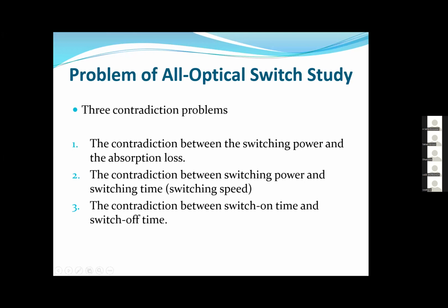The third one is the contradiction between the switch on time and the switch off time. In general, the switch on time of an all optical switch depends on the pulse width of the pump light. If the pump light uses picosecond or femtosecond pulses, the switch on time can reach picoseconds. However, because of the limitation in the carrier recombination time or the molecular moving speed, the switch off time is often longer than the switch on time, maybe by two orders of magnitude.